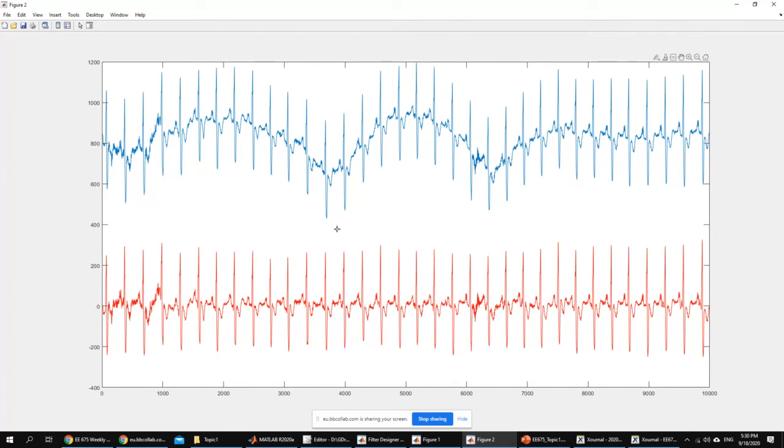Do you know what I mean? This signal has a DC value because it's all positive numbers, and if you compute the average, that is the DC value of the signal. The average of the signal here will be something like 800. Okay, when we pass this signal through a high pass filter, the DC is basically frequency 0, so it's going to be removed along with the other frequencies that were removed.